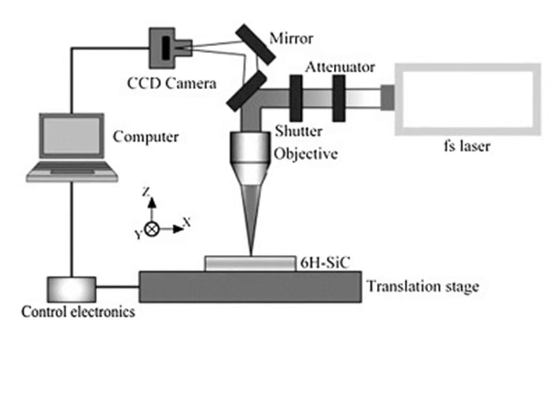So it can move in all three directions, X, Y and Z. Depending upon the shape that you want to cut, it will either move the laser beam, or, in this case, the material which we want to process is kept on a translation stage, so it will be moving the whole material. When the translation stage is moving, the whole material will be moving and the laser head will be stationary. So this is the basic schematic diagram which is used for cutting, drilling and welding applications.